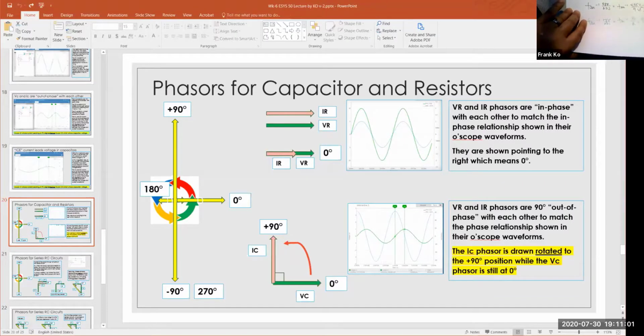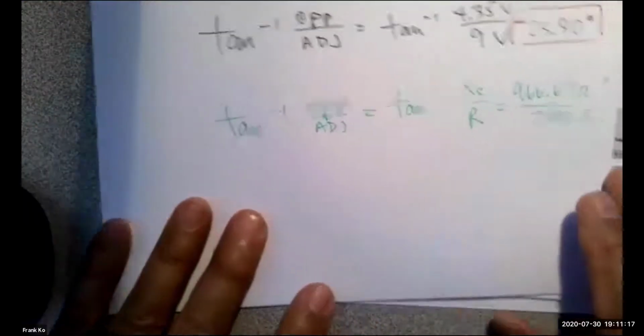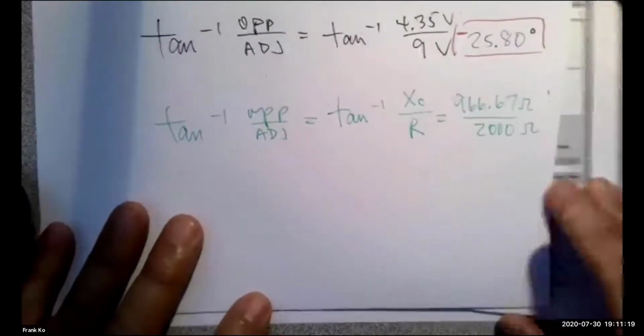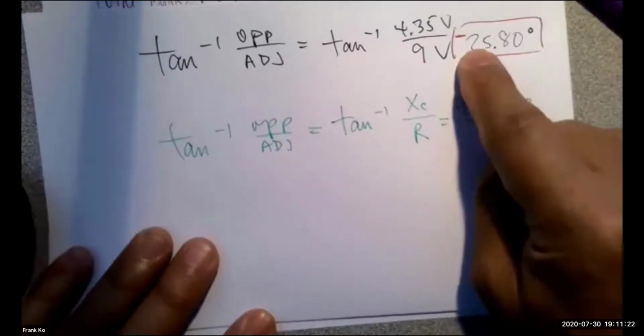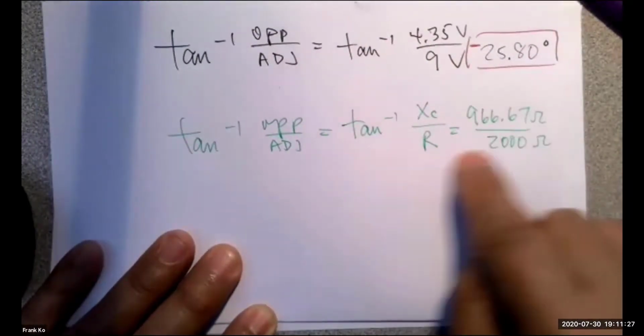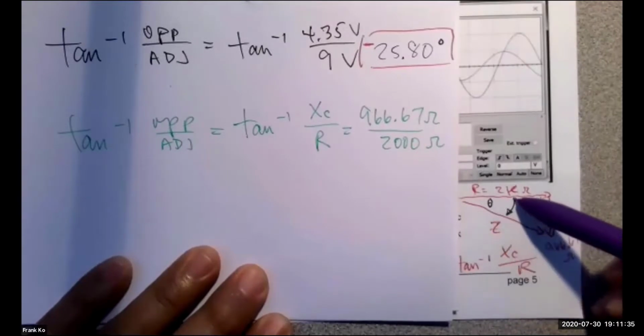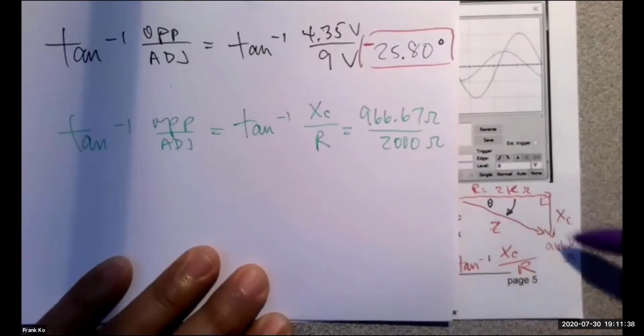So we happen to have this, and we calculate the angle. I'm still looking for a numeric value for the, oh, we have the numeric value, negative 25.80. As you're looking at what I'm pointing at, we already calculated a negative 25.80 degrees using voltages. Let's confirm that using the ohms. The ohms were from this triangle. We want to calculate this phase angle of theta. How far does the hypotenuse swing down based on these numbers?